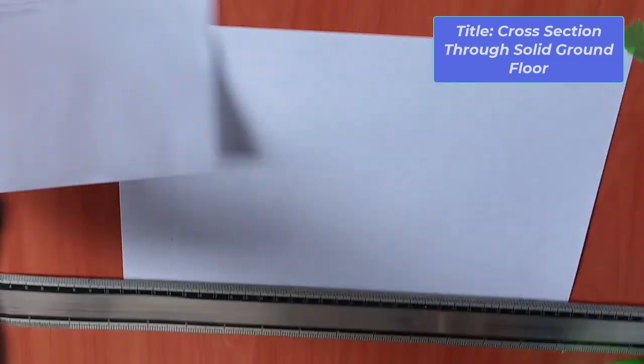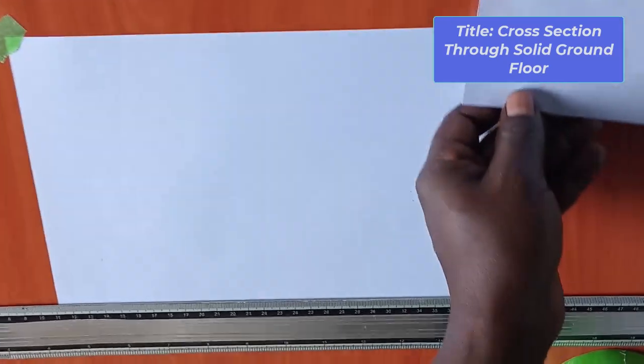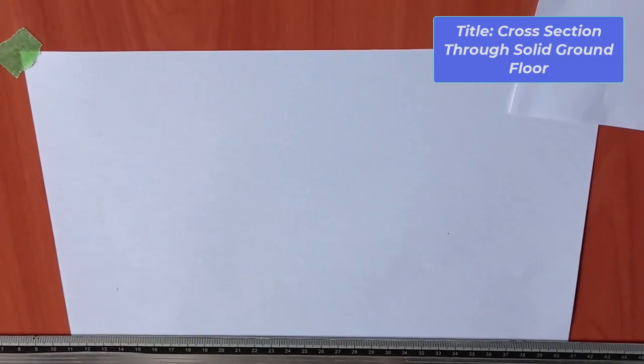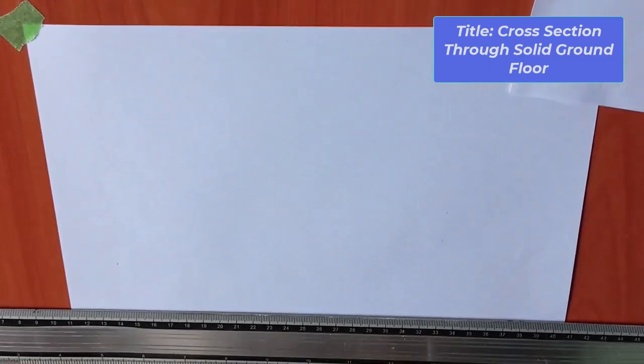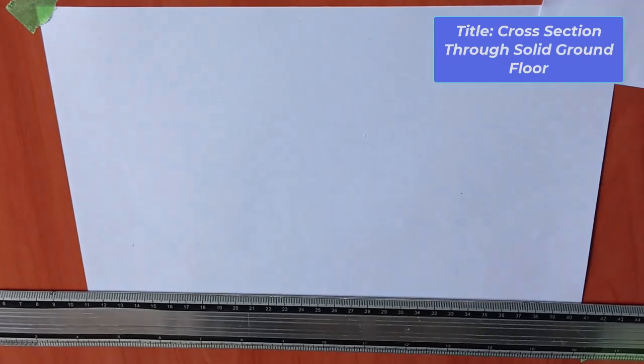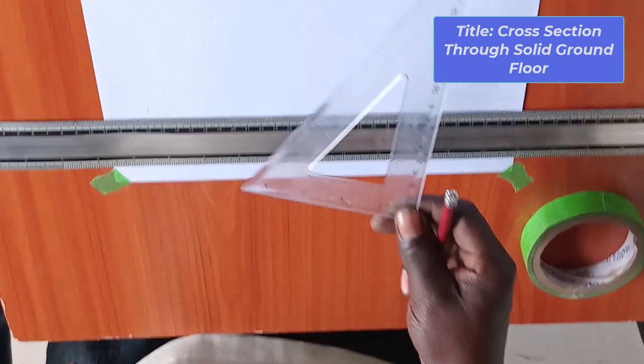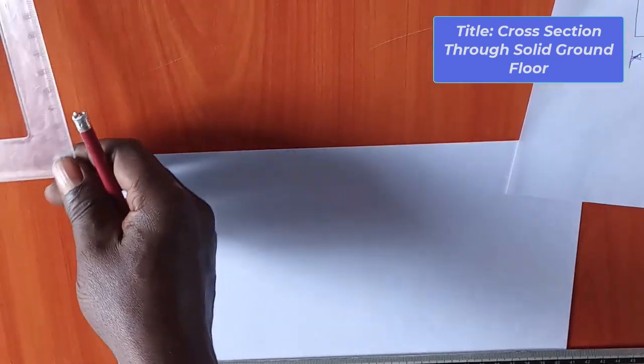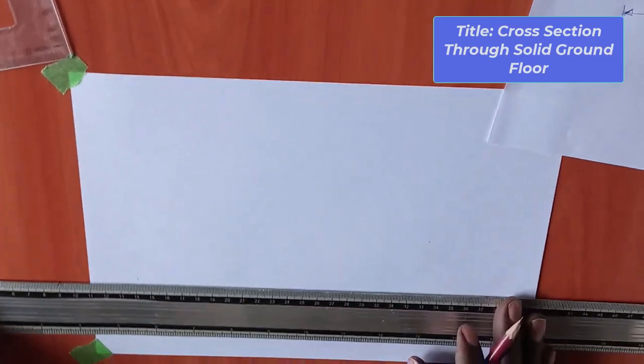So we are going to take this drawing, which is a sketch, and we are going to perform a complete scale drawing. And our scale that we are using today is 1 to 10. So we have to use drawing board, T-square, and then the set square. So I'm going to pick the set square, which we are going to use for our drawing. We are going to start with drawing the foundation line.